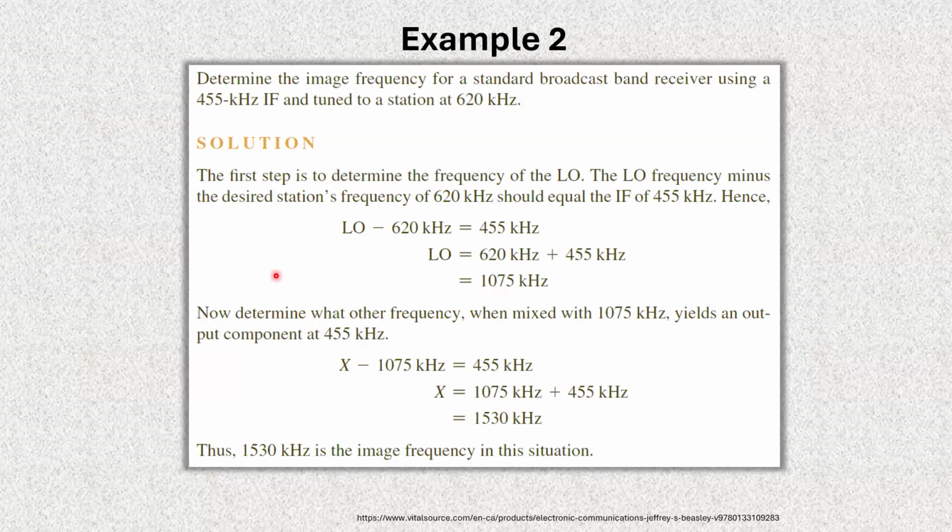By the way, how does the local oscillator know how to adjust? There are different ways of doing it. First was the mechanical way, the old 1920s way. Then there's also a mechanical solution where those capacitors and coils are put on a single shaft, so if you turn one, the others turn. Or you could use a VCO, a voltage controlled oscillator.